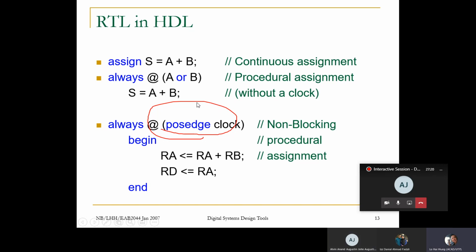Yeah. All right. Another thing that is commonly missed and confusing for beginners to Verilog is the assignment type. Notice that I write the assignment differently in this always block. This is just one equal sign, whereas this assignment is followed by a left-pointing arrow. Now, this denotes two different types of assignment. This type of assignment is called blocking. This type of assignment is called non-blocking.